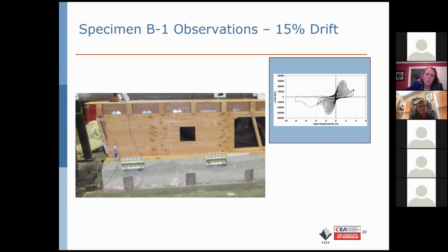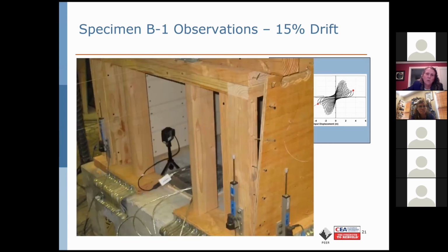And at that point, the plywood was really fairly substantially detached from the surrounding framing. It was only sort of nominally held in place at that point. But we still got further drift, and you can see it's still nailed along the bottom in this particular sheet, but free on the top. And sometimes it was nailed on the top and free on the bottom.